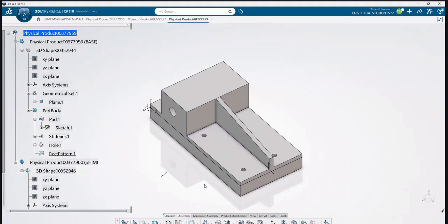So now that you saw what you saw, hopefully you won't think making the shims is actually that hard. More importantly, I want you to work in the assembly level, designing in context with the existing parts, not making two parts and then putting them together, but literally designing it to fit exactly with whatever you're trying to work to. Doesn't it make more sense to do it that way? That way I know it's linked to the other one, and if the other part changes, I don't have to go change the other one. Because the first assembly I did, right?